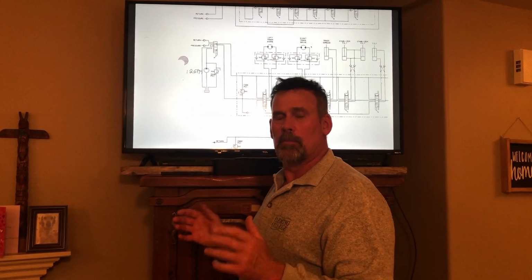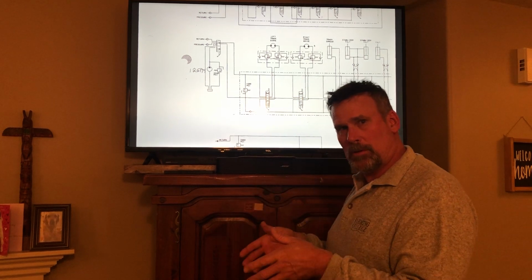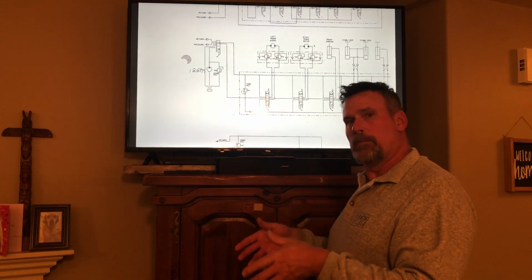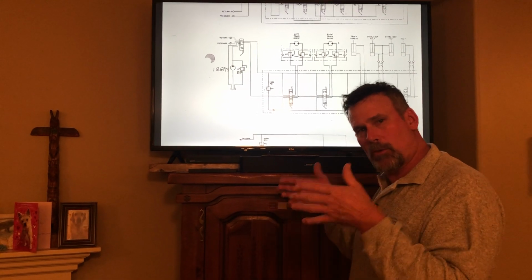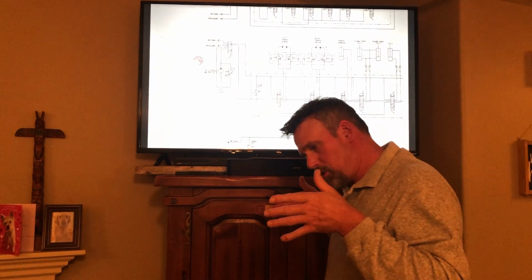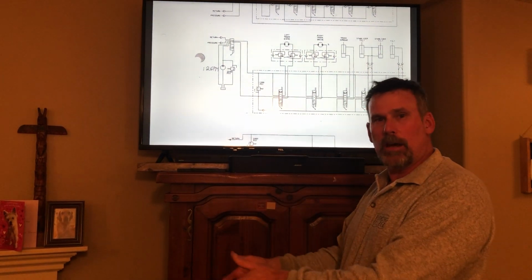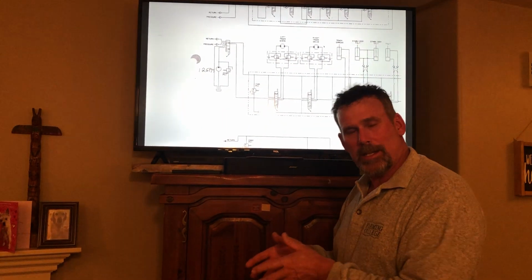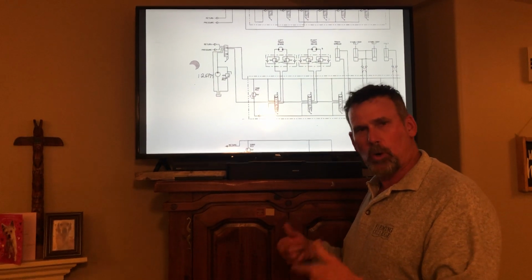Everything's good. But as soon as we crest the hill and we start to go down, now we don't need the oil pressure to move the rig because the weight of the rig itself is going to start to push it. It's going to take off and run down the hill on its own weight. It doesn't need your oil pressure anymore to turn those drive motors.